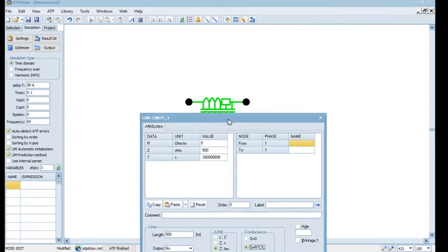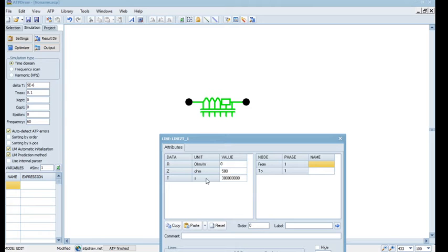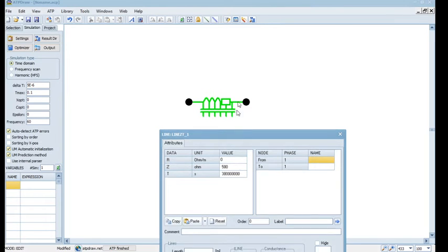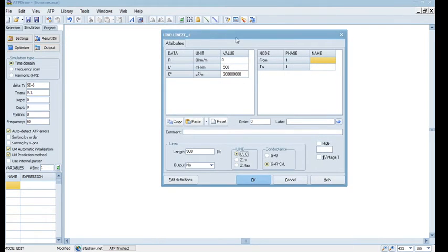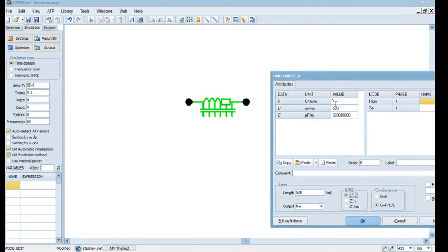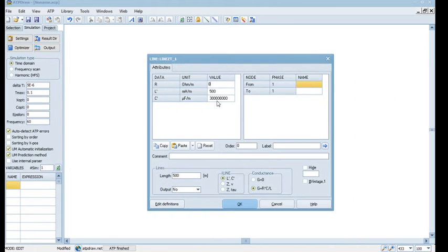For example, you specify a circuit parameter to this line. Let me just switch to L dash C dash because we already have that data. So I can specify L dash C dash and R to be 0 to begin with, let's say. But the transmission line has a resistance, let's say an aggregate resistance of 300 ohms for these 300 kilometers. So I can always write 300 ohms here, or I can attach it externally. And you can compare those two models just to see how it works. In fact, this will be more or less the same thing, and the same goes with the conductance as well.